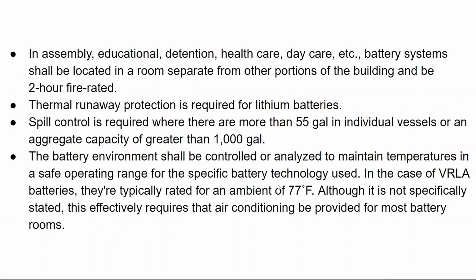There are additional requirements for battery rooms in areas where children are located. This one is kind of interesting. If your battery banks get sufficiently large so that you can fit more than 1,000 gallons of water into your battery, then you have to implement spill control. Now, I haven't come into residential systems that large.